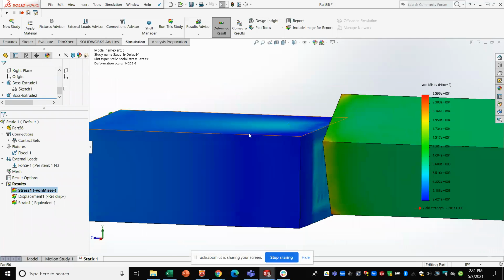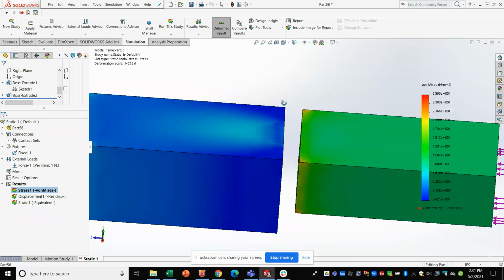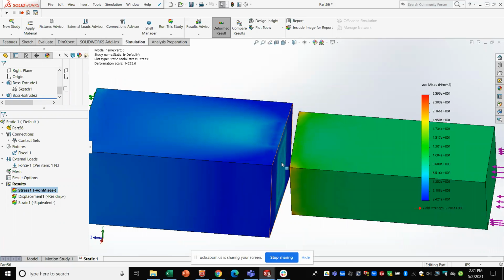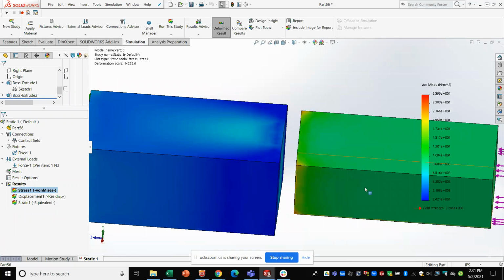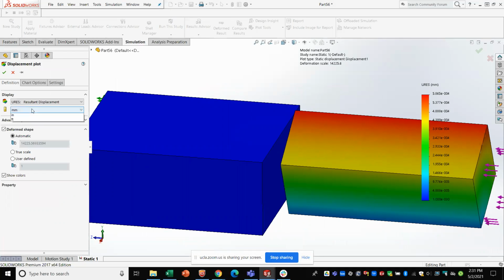Now notice how it didn't give me any errors about excessive displacements. That's because when I solved it with the gap option disabled, it was actually able to make this part here move. Here, I'm going to change this. Make this UZ.